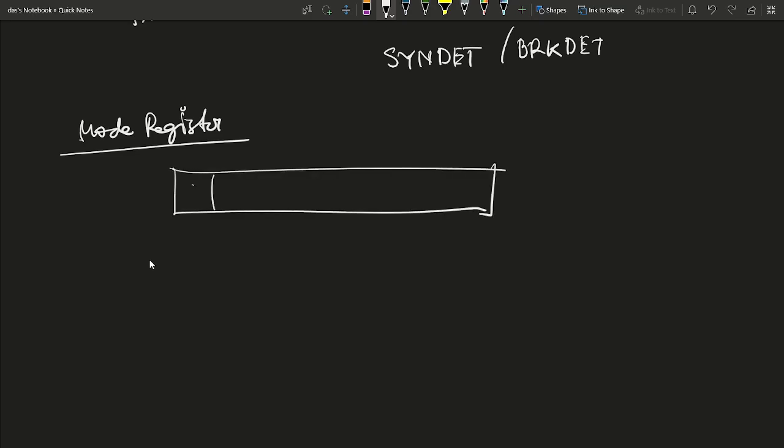Bits 7 and 6, these 2 bits, determine the number of stop bits. If this is 00, then it is invalid. If this is 01, then 1 stop bit. If this is 10, then 1.5 bits. And if 11, then 2 bits. So 1.5 bits is also available.